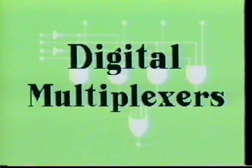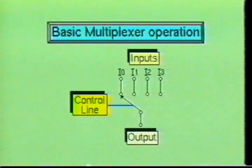The digital multiplexer is a combinational logic circuit containing 1 to 4 control inputs and 2 to 16 data inputs for each data output. Some multiplexers even provide complemented data outputs. Basically, the digital multiplexer performs the function of a single-pole multi-position switch in which one of the data inputs will be connected to the output at any one time. The particular data input being selected is controlled by the control input lines.